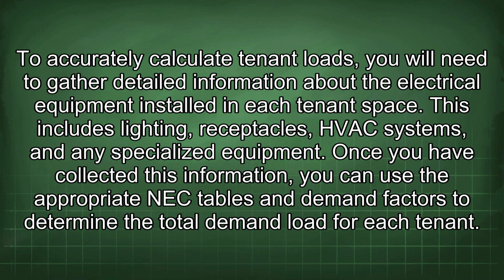To accurately calculate tenant loads, you will need to gather detailed information about the electrical equipment installed in each tenant space. This includes lighting, receptacles, HVAC systems, and any specialized equipment. Once you have collected this information, you can use the appropriate NEC tables and demand factors to determine the total demand load for each tenant.